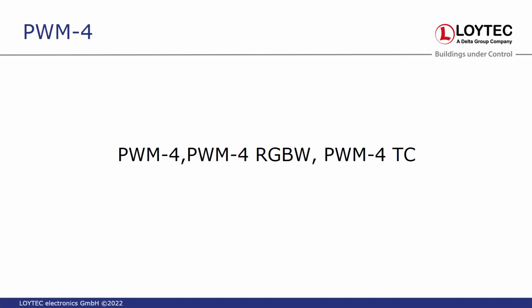Thanks, Pierre. Just for you to know, we have a project with RGB white, and finally we bought the PWM4. We put the RGB white strip, and it works really fine. The only issue is that we have 4 DALI addresses, and we have to combine all 4 addresses to get the correct color.